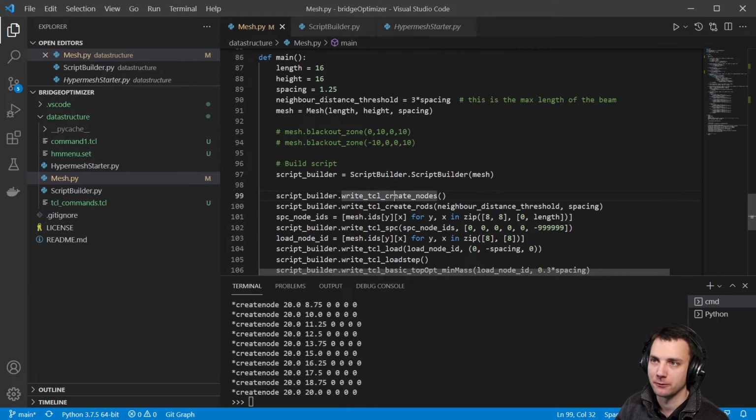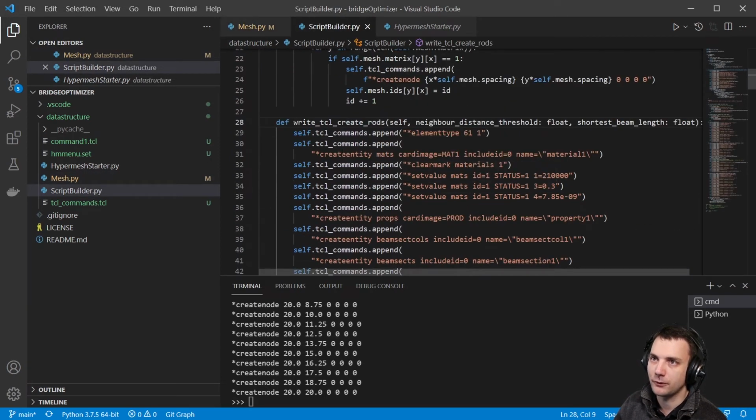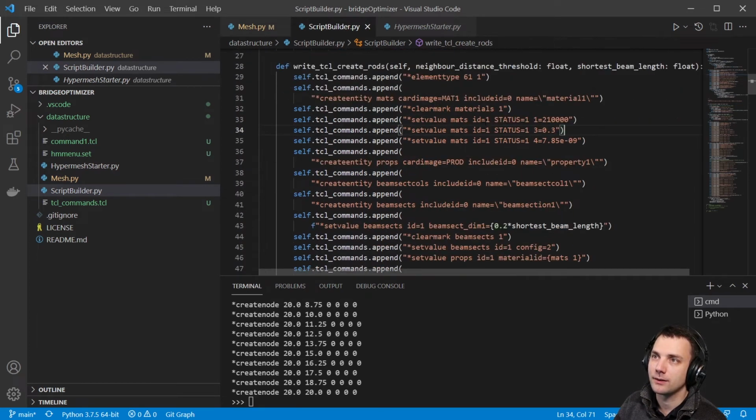So nothing fancy. TCL create nodes just creates the nodes based on a list of lists, and assigns an ID to the same column and row of a matrix. There's nothing fancy here. So the next thing is a little bit more complicated. It's creating the elements. And here it's called TCL create rods. And you have to give in a neighbor distance threshold and a spacing. Now let's see what this does. So first of all, what is done here is it creates a...